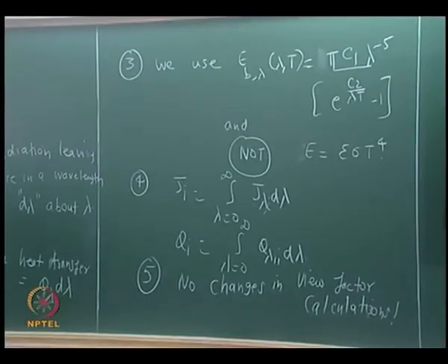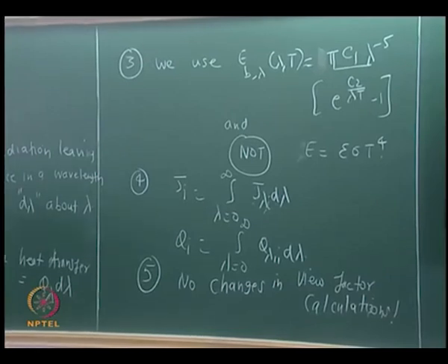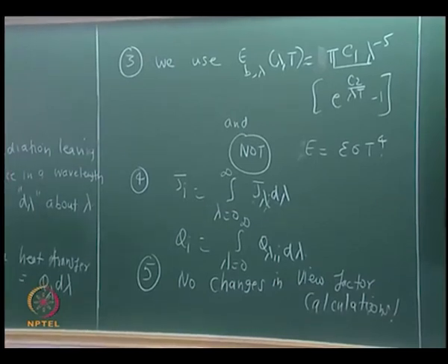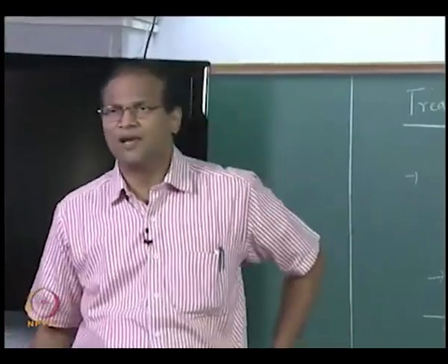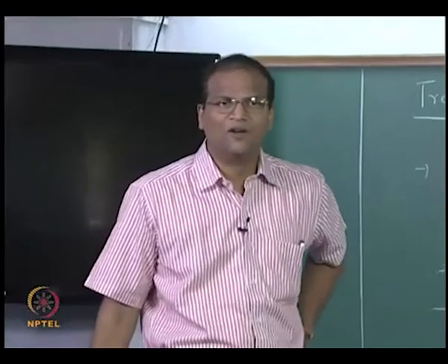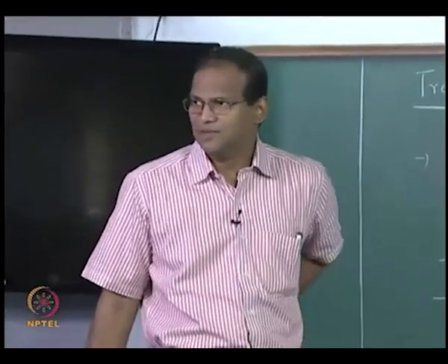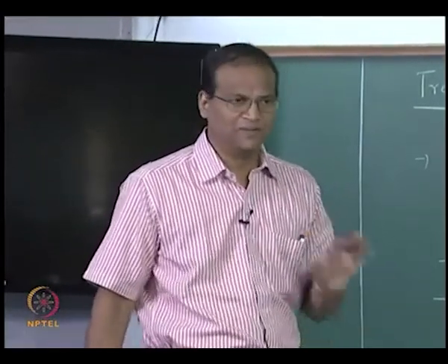then you will calculate for lambda 1 to lambda 2, then lambda 3 to infinity and so on. Then finally you can add up all the radiosity, add up all the q, that is a linear addition will work. Now I think quite a few of you must have got an idea of how the eventual equations will look like, but we will write out the formulation, we will solve a problem, then everything will become clear. We will just take the simple parallel plate formula, but now epsilon 1 and epsilon 2 are functions of lambda. I will just give a simple step function.